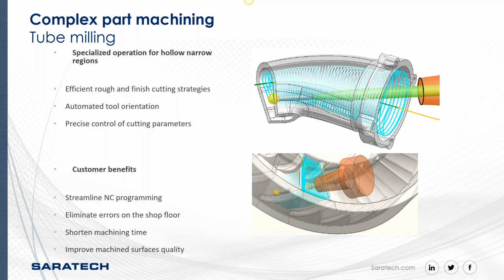Currently in NX12, it's more of a finishing strategy. You will have to use your standard 5-axis 3+2 style roughing toolpath to get that cleaned out, but you do have the advanced operation to be able to do that. And it's inside of one operation. You list 3 things: surfaces, all the surfaces you want to cut, what guide curve you want to follow, and then you fill your non-cutting moves and your cutting moves out, and generate the toolpath. That's all you do. And I'll show it better with the turbo milling.